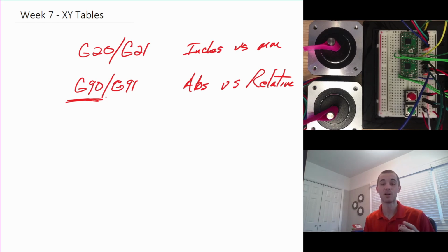And instead of putting in 20 different lines of G code, you can just call one and it will do a peck drill, which is slow stepping down and backing out of the drilling process. And then it'll switch tools over to a tapping mechanism and then tap it.